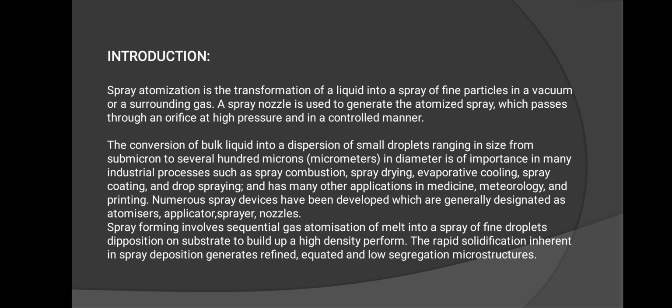Spray forming also involves sequential gas atomization of melt into a spray of fine droplets and deposition on a substrate to build up a high density preform. The rapid solidification inherent in spray deposition generates refined, equiaxed, and low segregation microstructures.